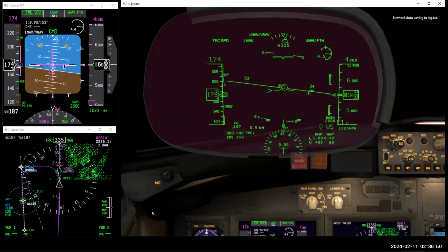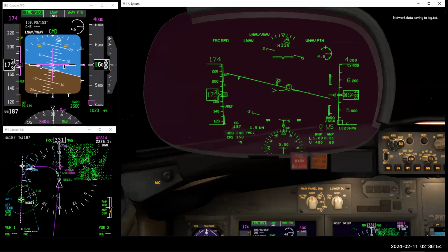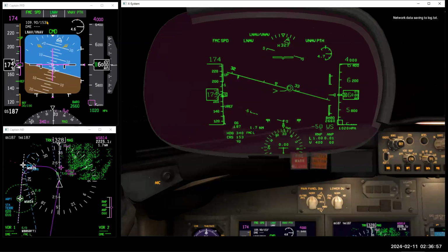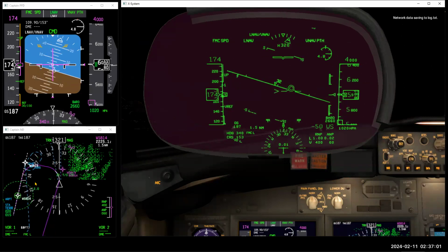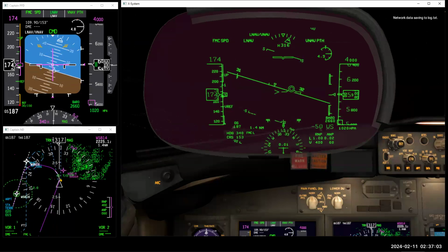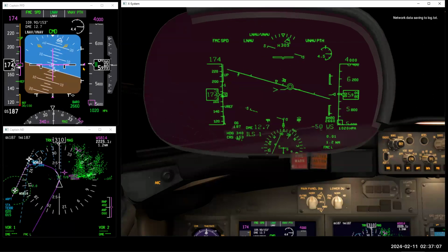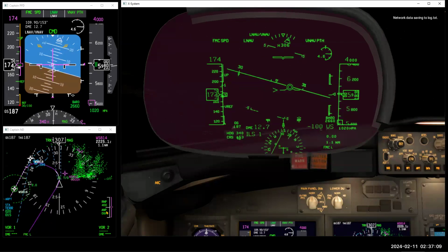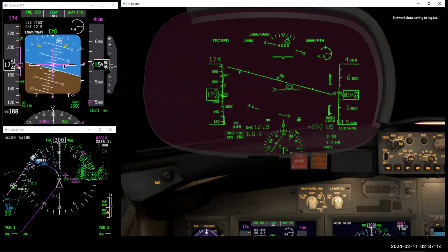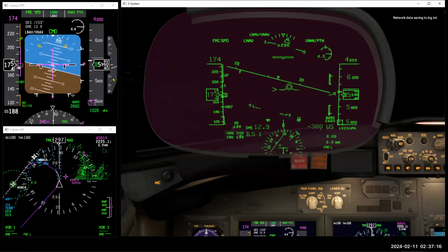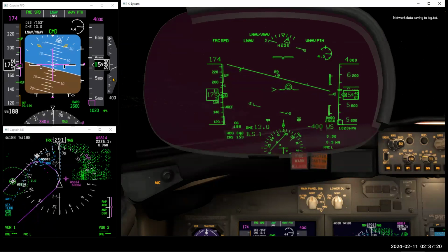If you notice on the nav display and on the HUD, we've got the glide path reference and FMC speed. We're in VNAV path. And we will start down at the top of descent. So we should notice a beginning of descent. There is the nav performance scales, and they're all indicating that everything is the way we want it, and descent is starting on schedule the way we have planned it.